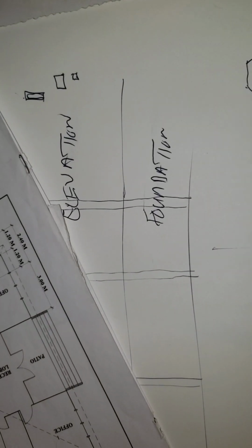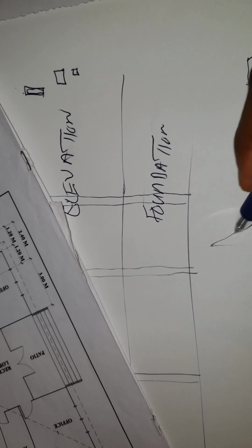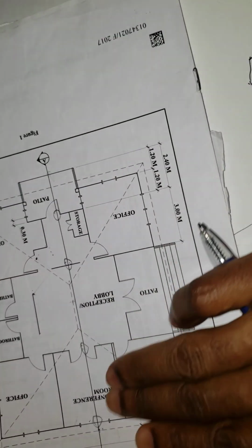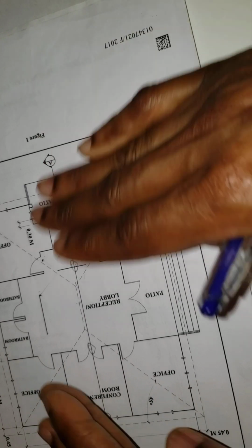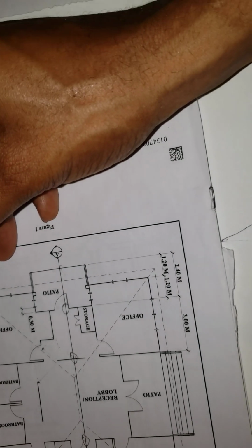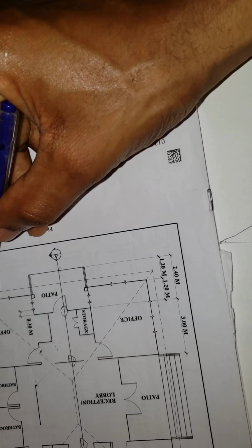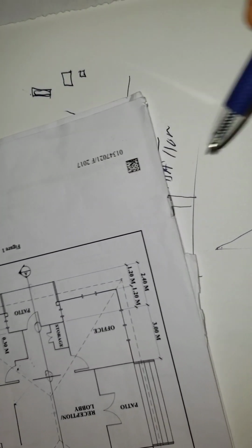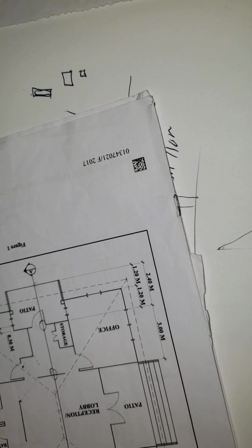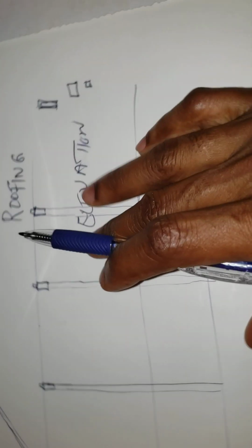So you could draw a line like this, draw this at 30 degrees, which is a typical angle for the rafters, the roof pitch. If the roof pitches 30 degrees, we draw this at 30 degrees. So this length would be the width. So you could draw a line at 30 degrees here, at 30 degrees here, and where both of them meet, we transfer this distance, and this distance will determine the height for this.